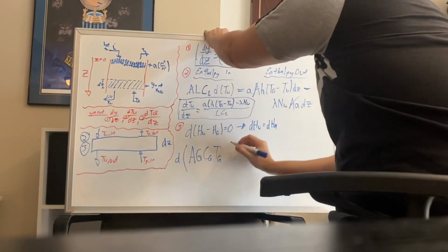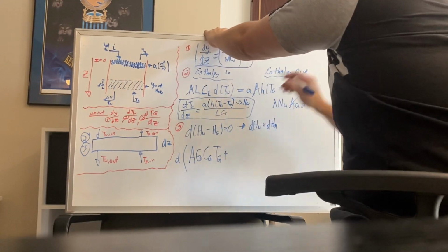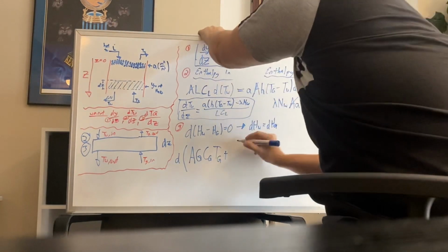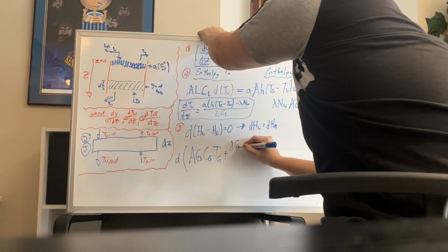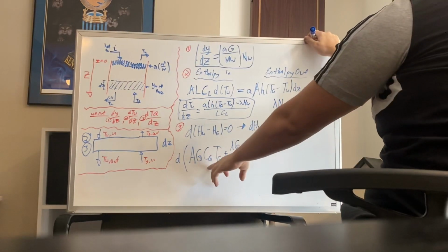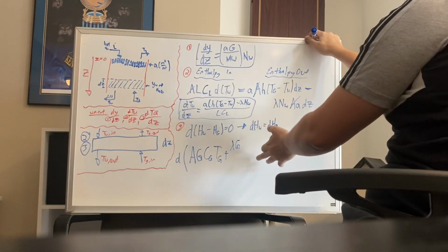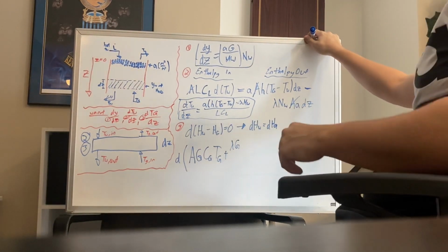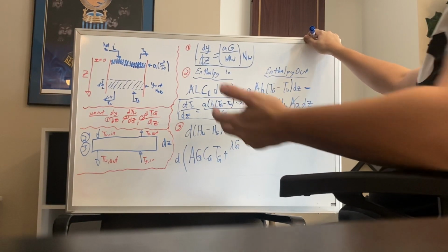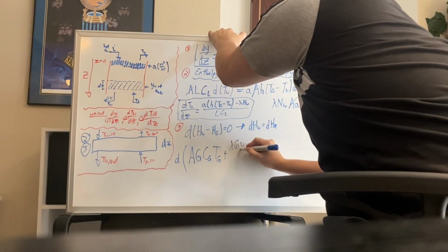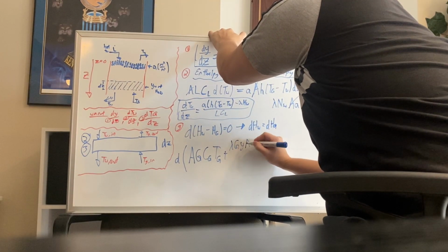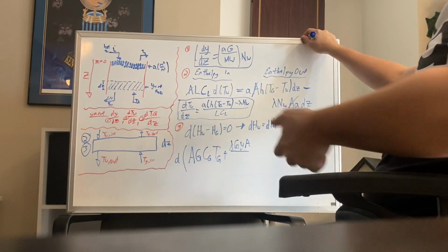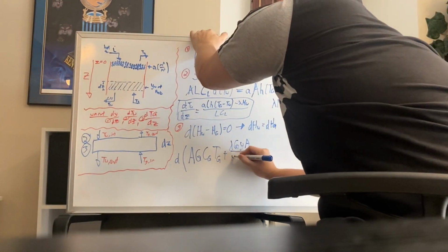So this is going to be adding on another unit, pretty much the inverse of this right here, where it's going to be the heat of vaporization multiplied by the gas flow rate constant that was also used over here. And we're pretty much swapping that out for the molar flux of water that we used up here. So it's pretty much the same thing, just kind of inversed. This is going to be also multiplied by the mole fraction of water, the cross-sectional area A, and it's all going to be divided by the average molecular weight that we have.